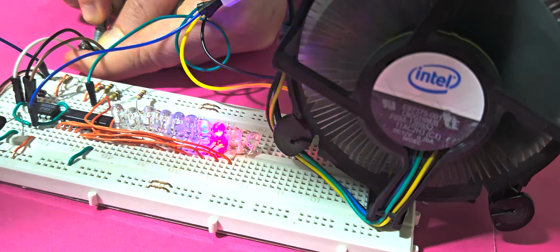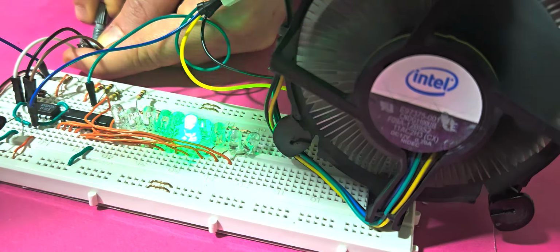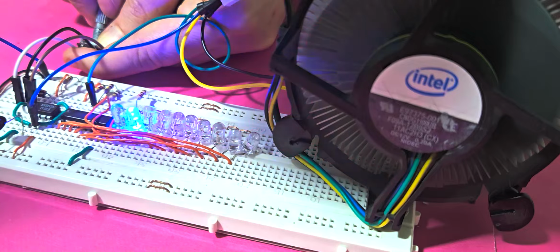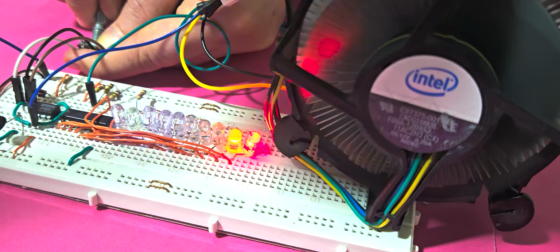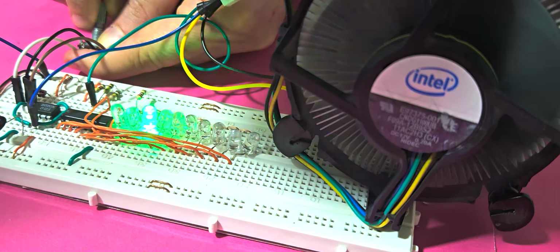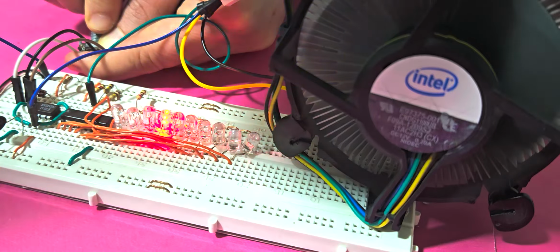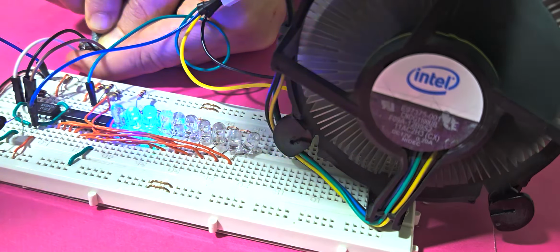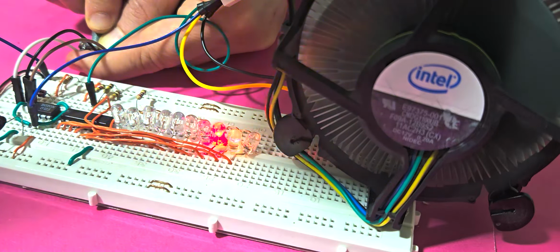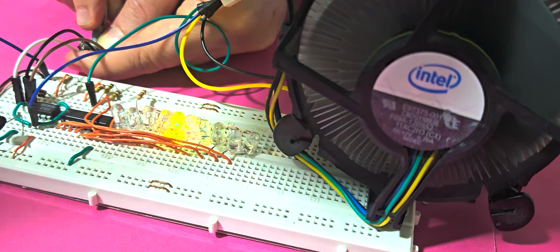In this video, the performance of the 4-wire fan is examined using PWM control. Also, the function of the TACHO pin in the fan is explained in detail. In this design, we first control the speed of a 4-wire CPU fan by using IC 555 and generating PWM pulses, and then by using IC 4017 and connecting the TACHO output of the fan to the clock pin of the IC. The performance of these two pins in the fan is displayed.